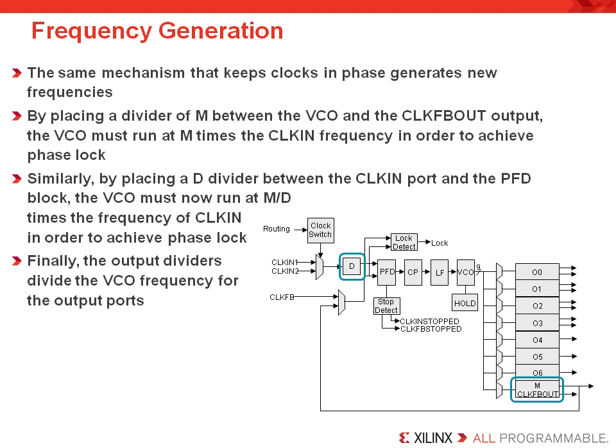If the frequency of the VCO is high, you can generate more possible output frequencies, and you generally get better jitter performance. But a higher frequency of the VCO does consume more power. So if a large value of M is required to generate the maximum frequency for the VCO, the jitter can also increase. So to help customers determine what's right for their application, we've incorporated a jitter calculator as part of the MMCM in the customization from the core generator or architecture wizard. So when you go to the core generator to customize your clock, look for it when you get to that utility.